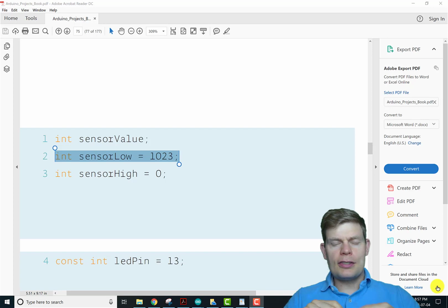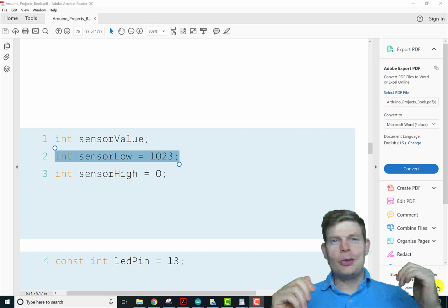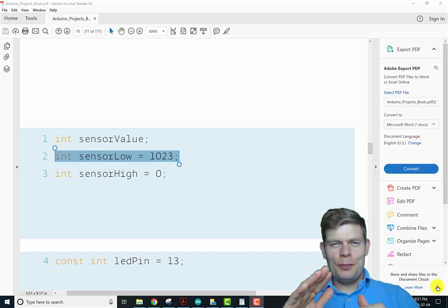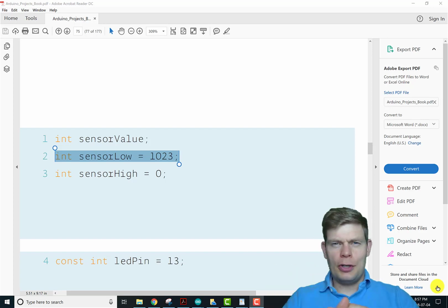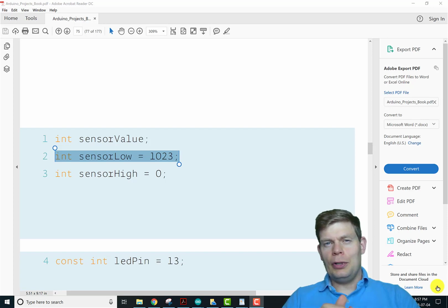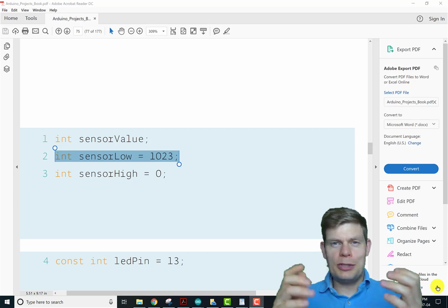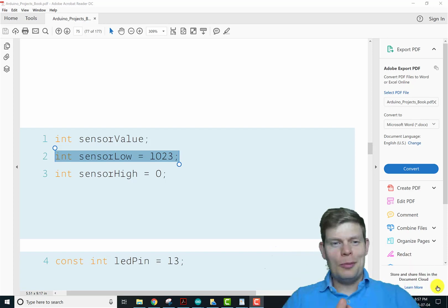I used to use code like this quite a bit for line following robots. You'd build your robot on your dirty mat at the school, and it would have much different reflectivity than the more recently made competition mats. If you hard coded it, you'd get the values all wrong, because the blacks would be less black and the whites would be more white when you went to competition. The lighting would be different. But with calibration code like this, it's perfect every time, no matter where you're using it, no matter how light it is or not. Anyway, let's talk about how it works.